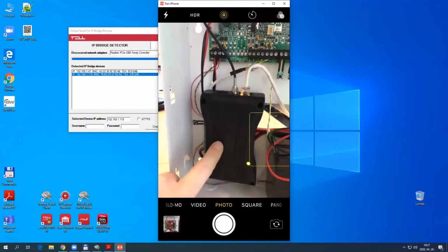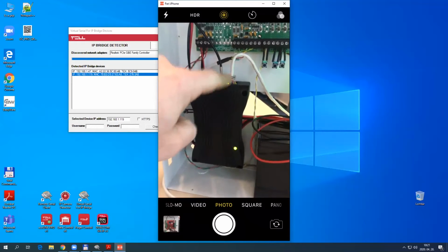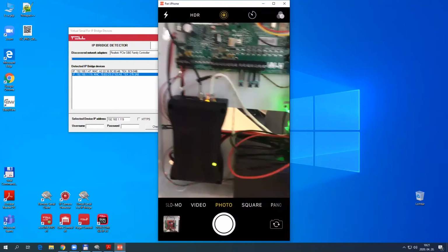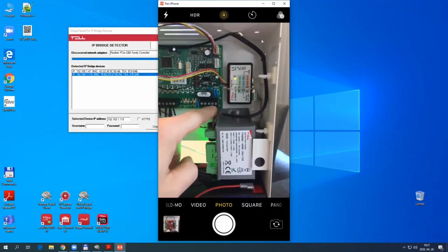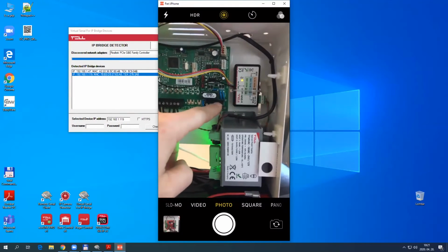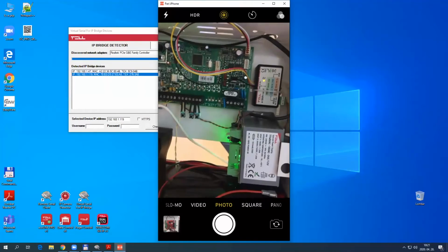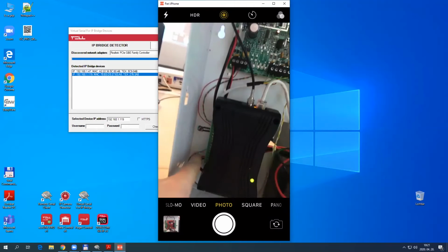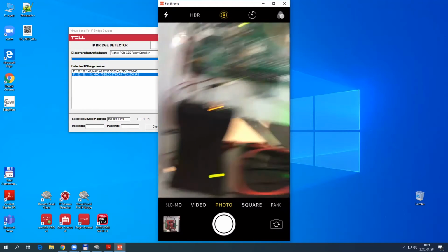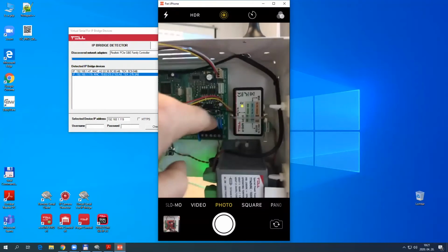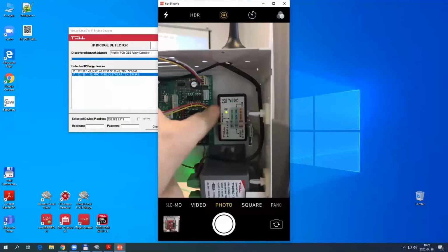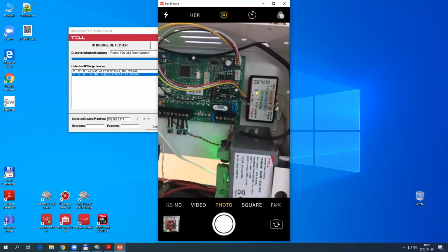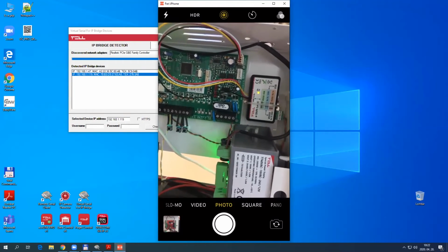So here's the IP bridge. It is connected to the internet using a LAN cable, and it is connected to the phone line input of the alarm control panel, through which it receives the communication from the alarm control panel, and the RS-232 port is also connected through a level driver interface to the panel, which enables us to remotely program the alarm control panel through the internet.